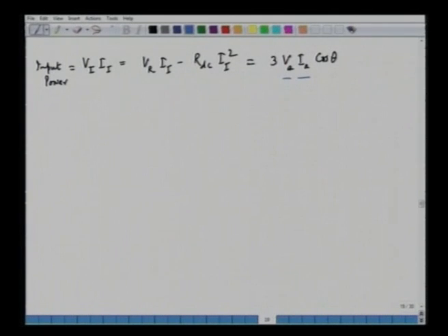Now let us draw the phasor diagram. If we draw the phasor diagram here, we can start with, let us say, the field axis. So this is our field axis, and we can say this is the D axis. We can show the field pole like this. This shows the field of the synchronous machine, and then the Q axis is at a right angle to the D axis. So this is our Q axis, and this angle is 90 degrees.